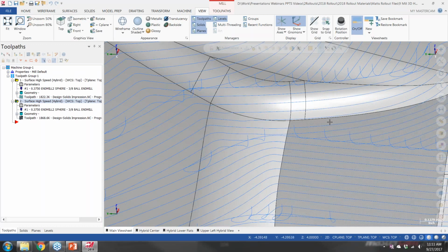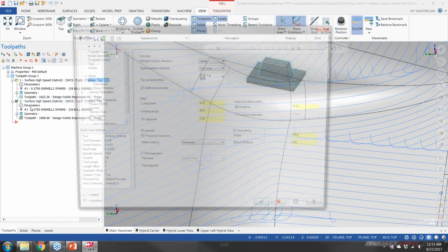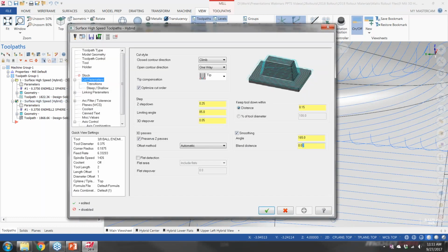Depending on the size of the part and the type of finish requirements, I would look into adjusting this. I found anywhere between about 5 thou and 50 thou is a good range to start playing with. I found anything bigger than that, it'll try to straighten out the toolpath too much and won't get close enough for a particular surface finish.